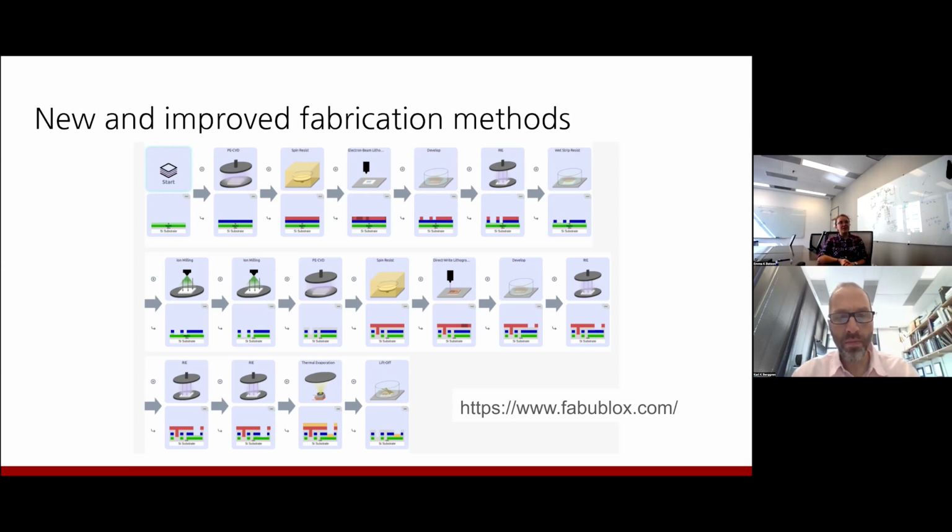The boron layer on top is required to maintain the stability of the underlying film and to maintain a smooth surface of the magnesium diboride. They have to do a post annealing process to improve the uniformity. It's a very interesting technique where they sputter these different layers alternating of boron, magnesium, and boron, and then they anneal it all together into the magnesium diboride layer.